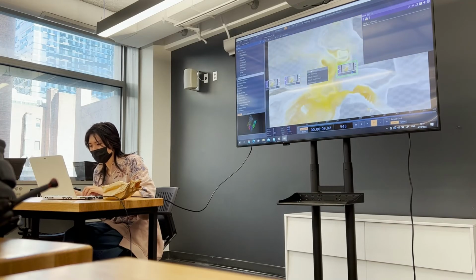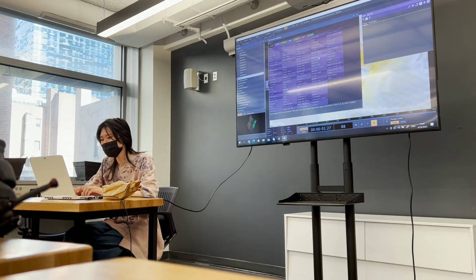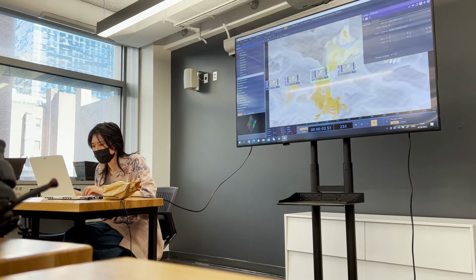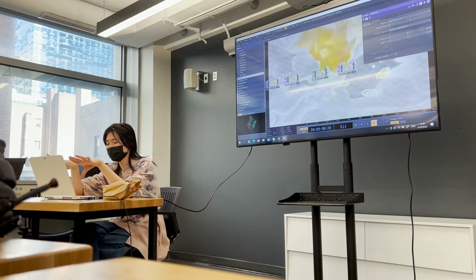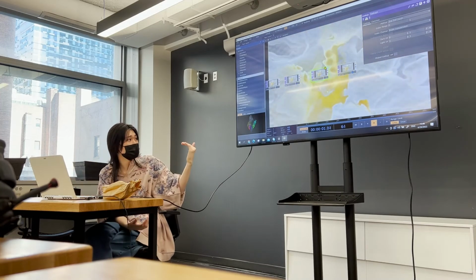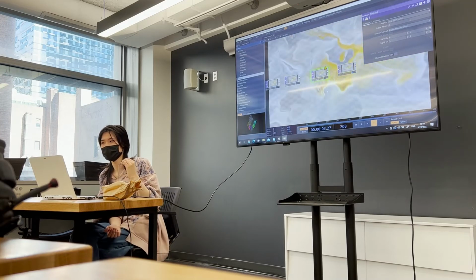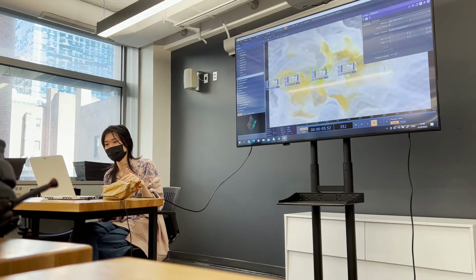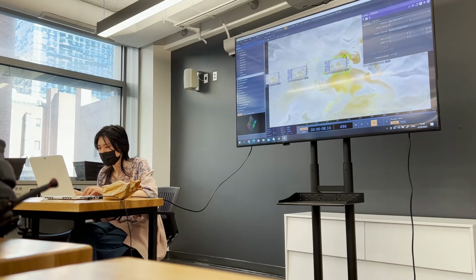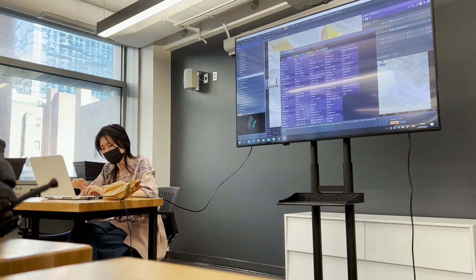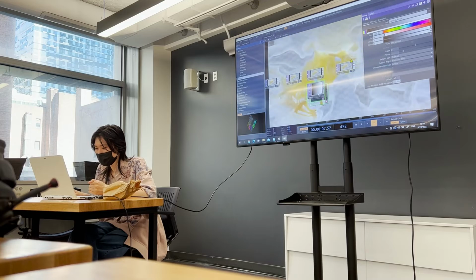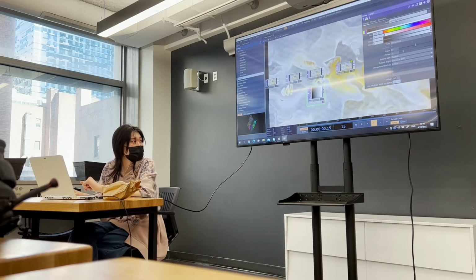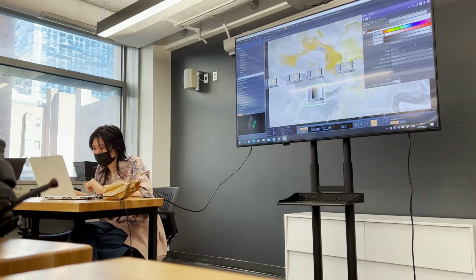So for this null, we're going to add a lookup. What Lookup does is essentially it looks at the luminosity of this input image 1 and uses it as an x coordinate to look up the second image. The easiest example would be adding a ramp to the second input. A ramp essentially generates a ramp. And if we connect that to the second input of lookup,